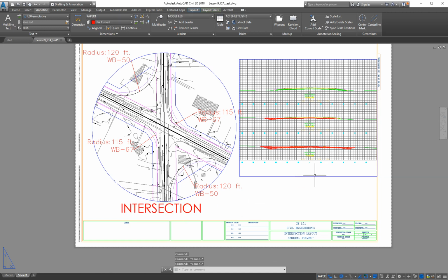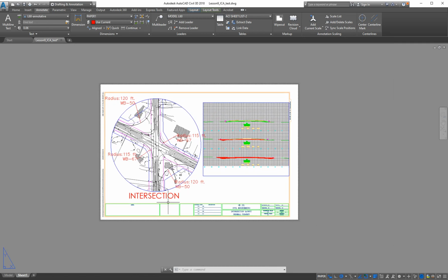You'll also do one over here that says cross section. Again, all of this stuff is living in paper space, and we're just viewing through these windows what's in the model space. We're not actually adding any of this text into model space, so it's not screwing it up the next time we want to use it for some other drawing. I'll let you do the one that says cross sections over here, and that brings us up through 15. You're going to make a plot now at this point called plot 4.